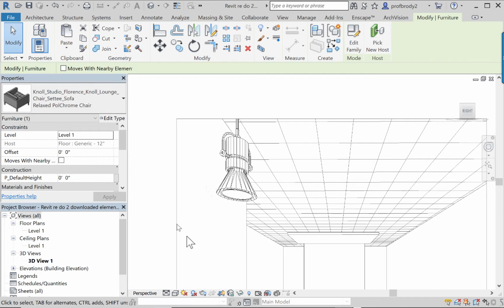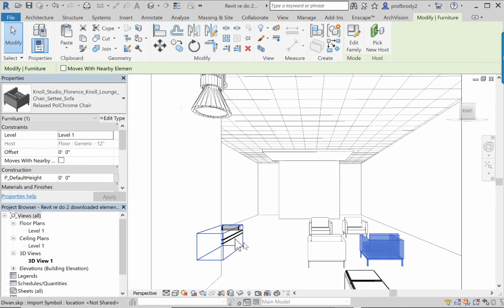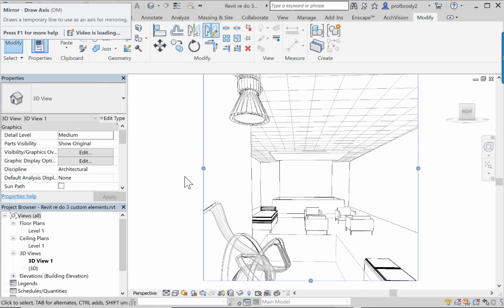If the model is giving you trouble, and I believe one of these models did, I export it as an AutoCAD file format. And that often gets rid of some of the weird problems of, say, nested groups and components and things like that. So anyway, there you go. You have examples of me trying to save time by downloading furniture that's pretty close to what I'm looking for.